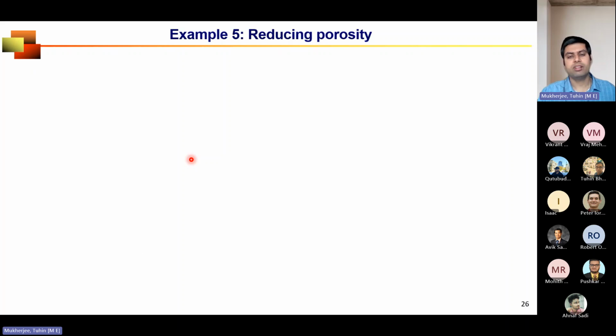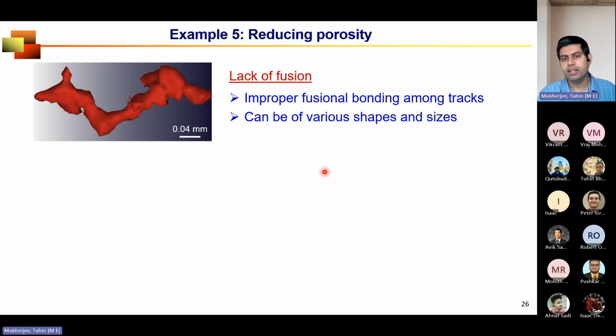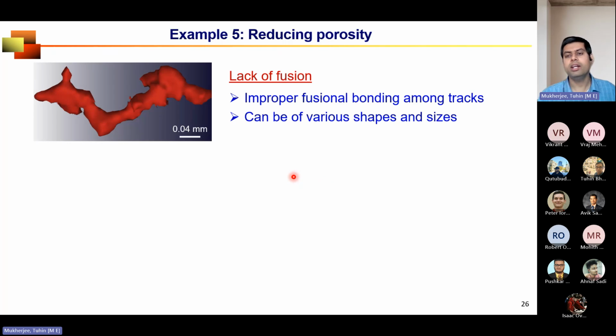Okay, so after microstructure and property, the remaining examples mostly focus on defects, because defects, apart from the microstructure, largely control the mechanical properties and performance. For example, porosity. If you have pores inside the part and do a tensile test, the part will fail before you expect. So we need to understand porosity. To me, there are 3 types of porosities in additive manufacturing, and we can visually distinguish among those 3 types of defects. First is lack of fusion.